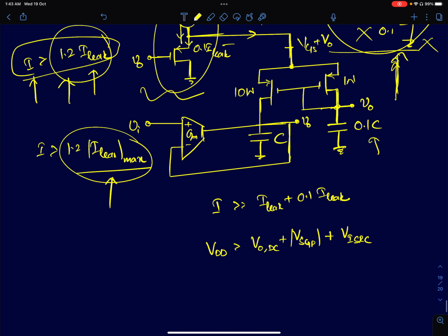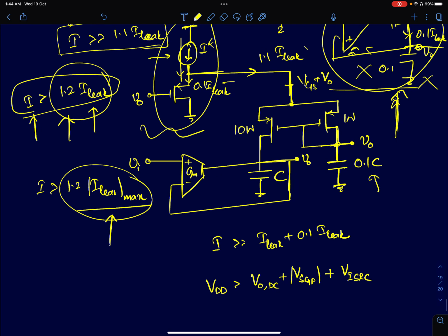So that's the second idea that I discussed. In fact, this is the question I posed first. It might look a bit complicated, but if you reduce it to its fundamental constituents, it's a very simple idea. All I had to do was design a current mirror. That's how I thought of this idea. I said, I just need a current mirror which has to measure this current and inject it into the main capacitor. Then the next thought process is: what should I do to ensure the voltage across the replica capacitor is exactly equal to V0? That was my thought process, and this circuit was the outcome of that thought process.